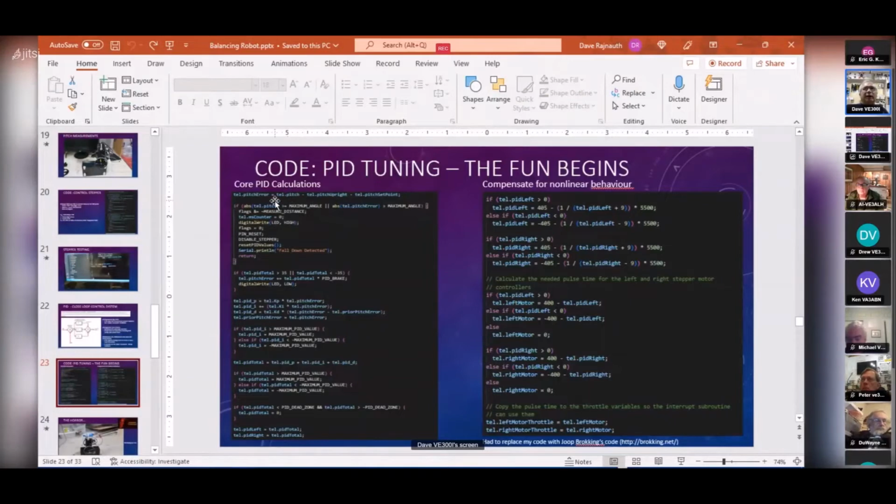What the IMU is measuring, what you're supposed to want, and this is just a correction point that I had to add in. And here's the P term, the pitch error times the constant KP. Here's the integral term, where I'm summing over all the errors.